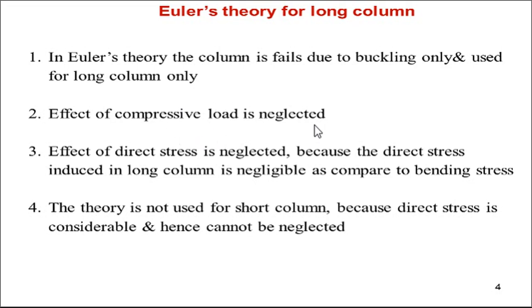The effect of compressive load is negligible, meaning whenever the compressive stresses are very small, the compressive load is also neglected. So the effect is totally neglected in Euler's theory. The effect of direct stress is neglected because the direct stress induced in a long column is negligible. In a long column there are only bending or buckling stresses, and direct or compressive stresses are very negligible. That's why this effect is also neglected.